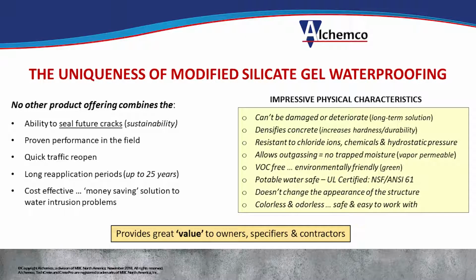It's completely VOC-free. And again, one of my points about being a waterproofing agent, not a protectant material, is that we have dozens, actually hundreds, of water tanks and pools and areas where we have water 24/7. About the hydrostatic pressure, we have tests up to 1,300 feet of water pressure, so 400 meters. It's really impressive that you have 1,300 feet of water pressure with no leaking. And it's not going to change the appearance.